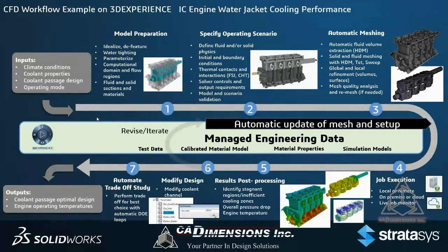From there, it's a separate step to mesh, right? So we create our fluid volume, make sure that everything is watertight if we're doing an internal analysis like this engine cooling analysis. And then our separate step is to mesh. The platform does it in one step. It will take our flow domain, take the abstraction shape, and mesh it at the same time. And it's a different mesher.